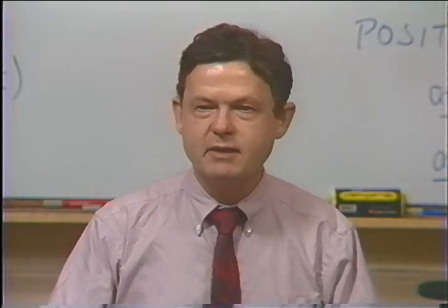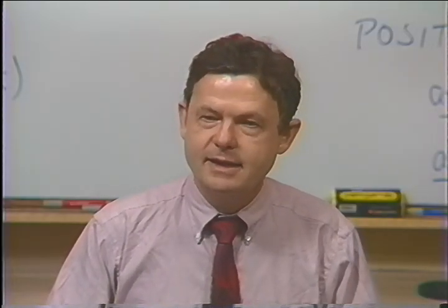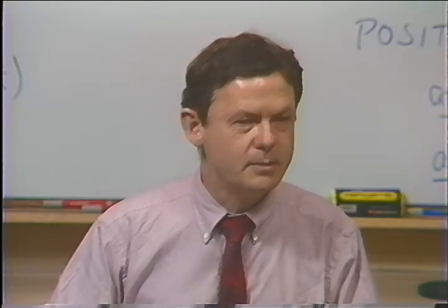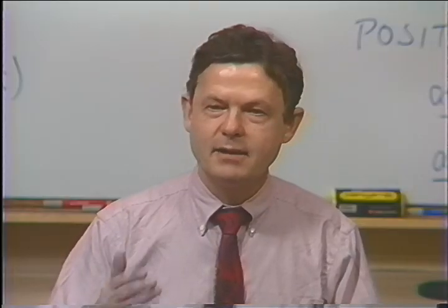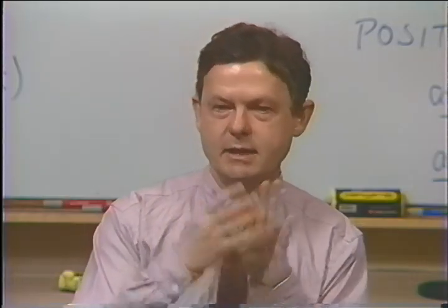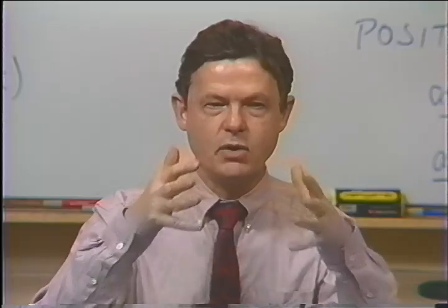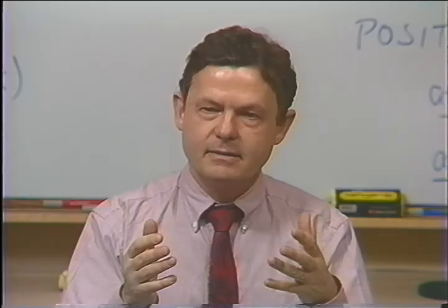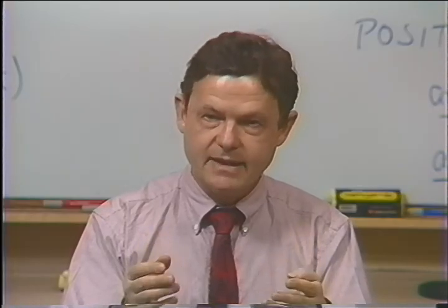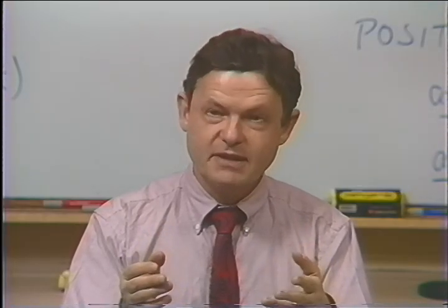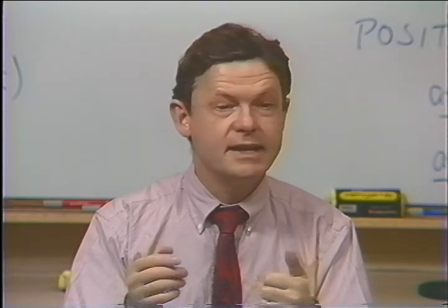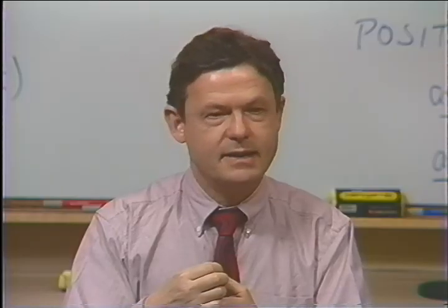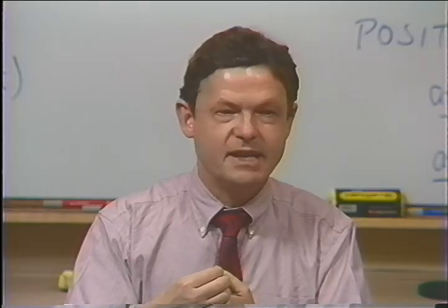An experiment to produce equibiaxial extension is also bubble blowing, and I assume most of you did that. Forming a bubble, forming a sheet of chewing gum in your mouth, clamping it with your lips, and then blowing against that. That's also equibiaxial extension. People have used that to produce equibiaxial extension in a real apparatus: Denson at Delaware and Dealy at McGill University.